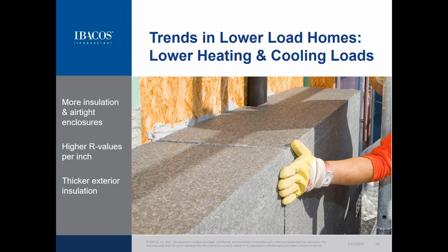Well, energy codes are pushing it, and homes are being insulated higher. So insulation in the walls, roofs, and foundations, R-values are increasing. We're seeing a new addition of continuous insulation on the outside of wall systems, which requires thicker insulation on the outside, but ultimately it's creating smaller heating and cooling loads. And with that, the indoor loads, whether heating or cooling, are getting a lot smaller.